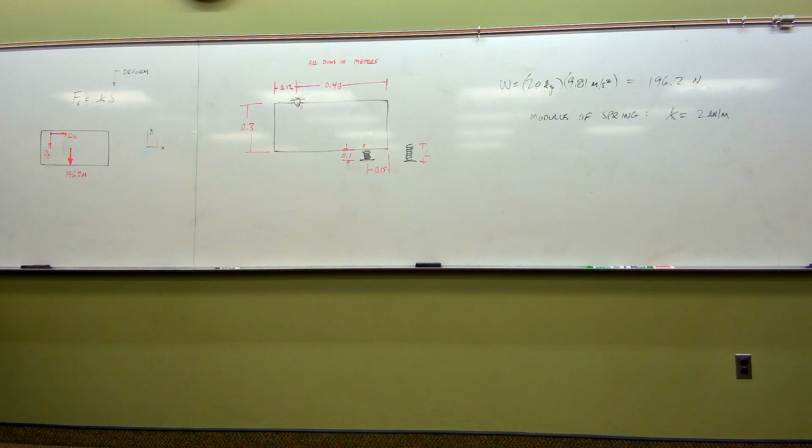Doing fine with that so far. And again, folks, remember, it's a pin. The standard representation is an X force and a Y force. If you ever forget that, you can always ask yourself, if the pin was still there, can I move it in the X direction? Nope, X force. Can I move it in the Y direction? Nope, Y force. Remember that.